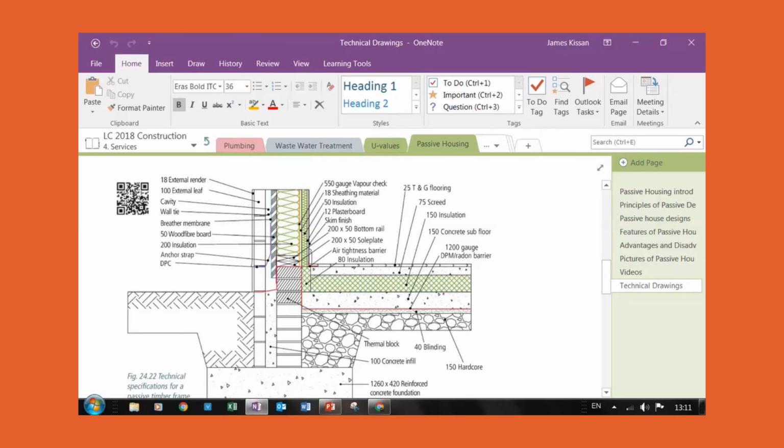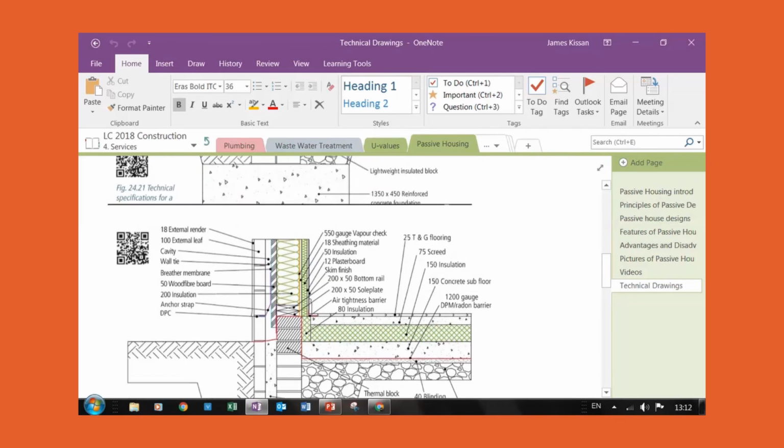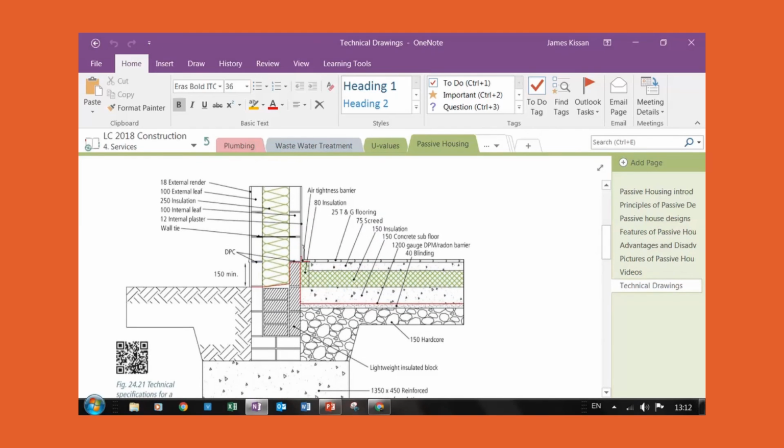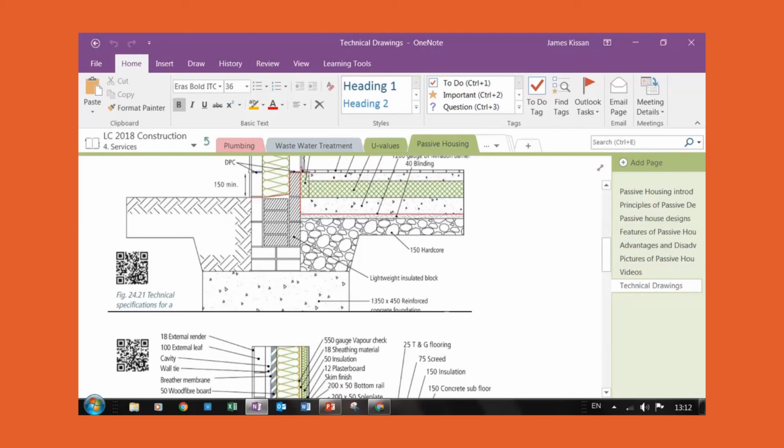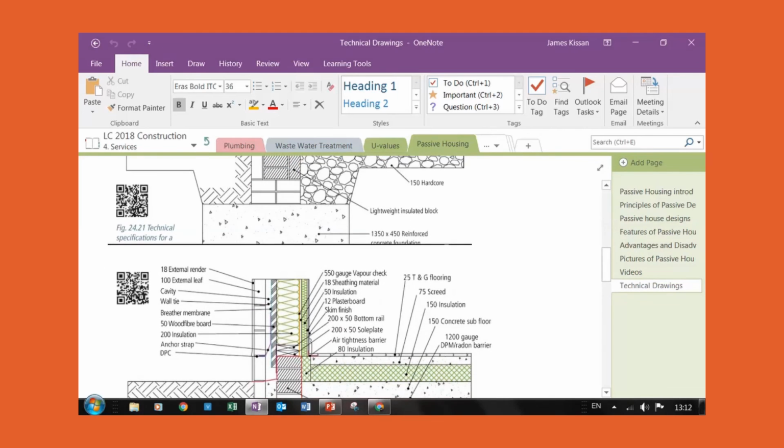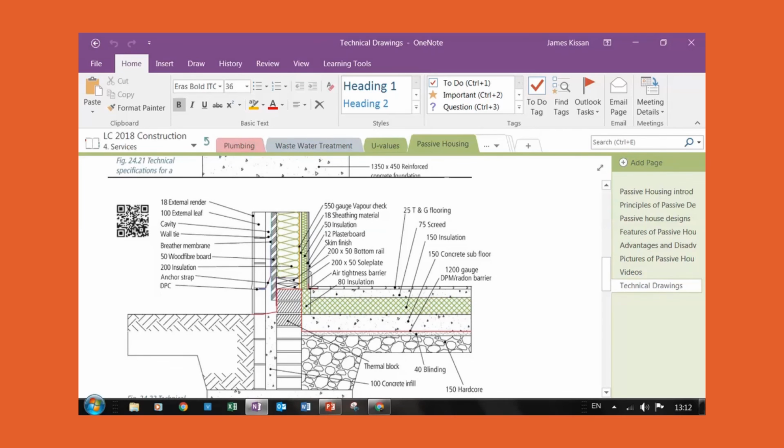Then we have our sheeting material inside. We have a vapor barrier placed in there. And then on the inside of the wall, we have a plasterboard slab with insulation stuck onto that. And that's all fixed onto this internal wall. So it's a really complicated detail. And this is why a lot of passive houses now are going back to a more traditional method of using blocks, because it's actually an easier detail to meet passive housing standard. Now, this section here, the timber frame section, is still all built in the factory. So it'll arrive on site like this.